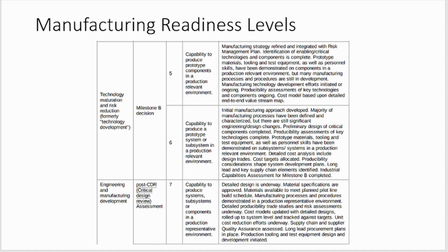Moving on to the middle section, the processes begin to differ. As mentioned previously, the prototype costs will be much higher with the vacuum-assisted high-pressure die castings. This will serve as a tough bar to overcome for smaller companies that cannot afford it and will seek slower but cheaper options that are more realistic. However, basic high-pressure die casting can move farther up the manufacturing readiness levels for both large and small companies by having a lower bar to entry and transitioning into easy-to-work-out processes.